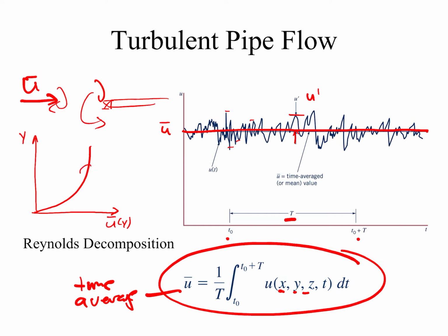Turbulent eddies are going to take momentum from up here, this high-speed fluid, and bring it down lower. At the same time, eddies are going to take these low-speed fluid elements and move them to some other part of the flow. And as that's happening, that is what's causing these fluctuations about the mean in this time trace. So I'd like you to think about it in that way. We're having mixing going on, and it's not just mixing of things like dye.